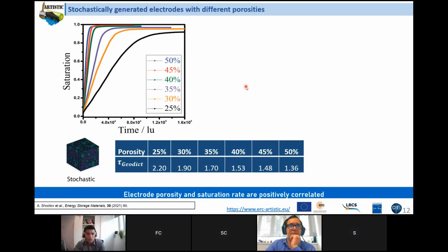just controlling the porosity. As expected here, the higher the porosity, the saturation goes close to 100%, and it fills quite fast. By decreasing the porosity, the electrolyte saturation slope goes even lower, and it goes slower, and it doesn't reach 100%.